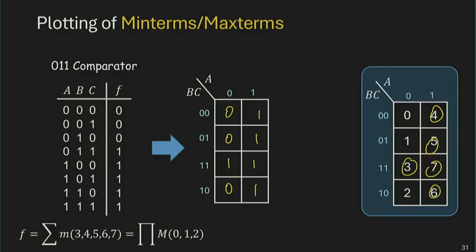Again, you can follow this gray code ordering to give them adjacent binary designations: 000, 001, 011, 010, 110, 111, 101, 100, and wrap around, they're also neighbors. This is one gray code ordering. You have multiple equivalent gray code orderings. You can shuffle it a little bit, shift it a little bit, rotate it a little bit. But this is essentially what you will get.